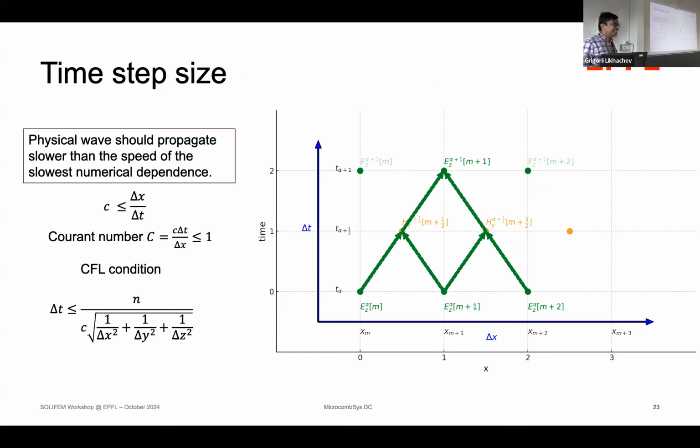Any questions? Okay. Generally it can be a uniform structure, or it can be a non-uniform structure. When you discretize your system, you don't just discretize it uniformly. The mesh size can also be non-uniform. Wherever you have a high density of photonic components, you can discretize it to be very closely spaced, and there the time step would of course be very different. So the step size can be non-uniform, to answer that.